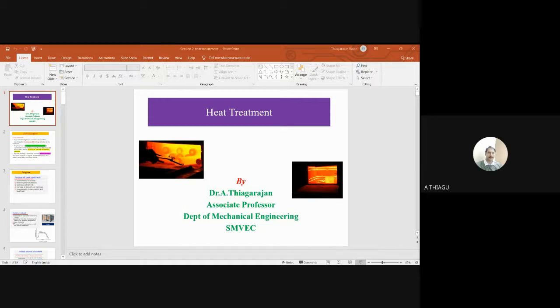So these are the various problems that may occur. Okay, so this is where we have to prefer the heat treatment process. Is it right? So the main objective is to make the metal soft, to refine its crystalline structure and to remove the internal stresses. So what materials are most suited for this full annealing process? You can take steel castings or steel ingots. Most of the steels come under this category, full annealing process. This is the information I just want to share.